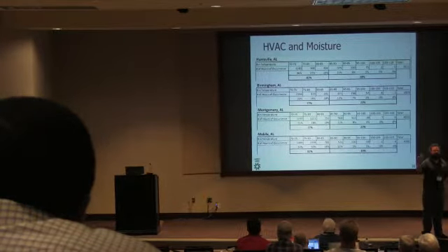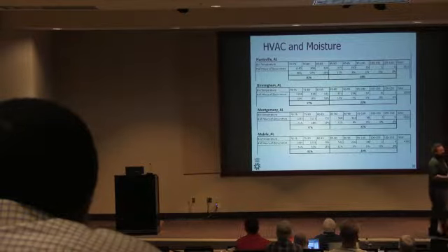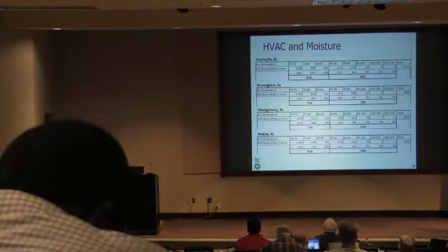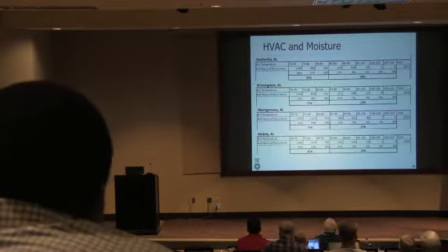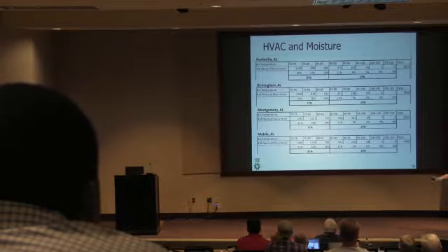I mentioned this earlier. Our HVAC systems are really good at making cold air, right? Bam, cold air. The problem is they're not very good at dehumidifying. And the comfort factor that we're often trying to deal with inside our homes is relative humidity, more so than it is temperature. A 70-degree house with high relative humidity is clammy and uncomfortable. A 75-degree house with 50% relative humidity feels great.